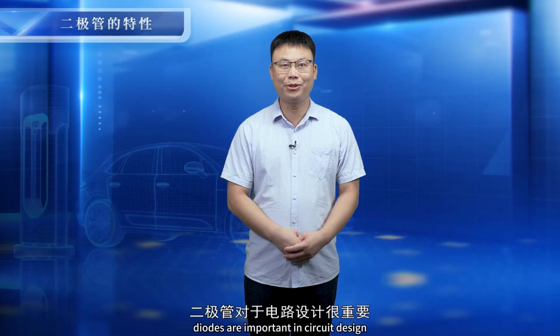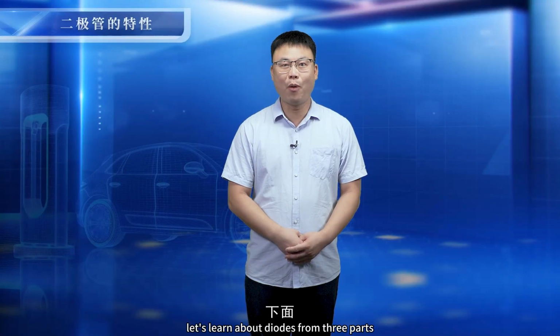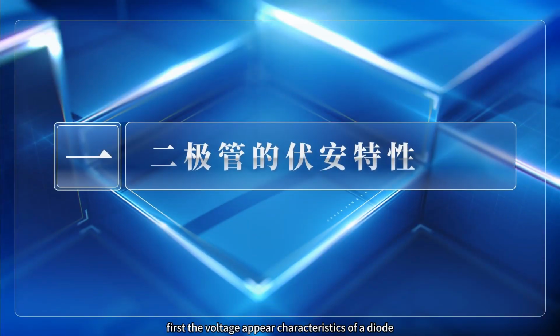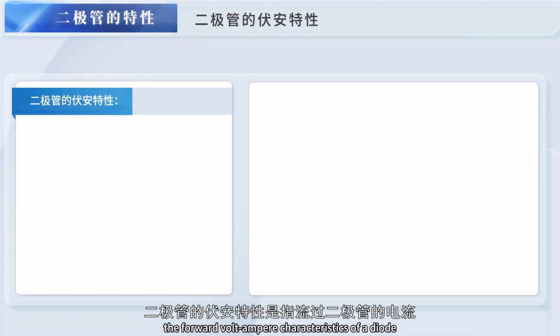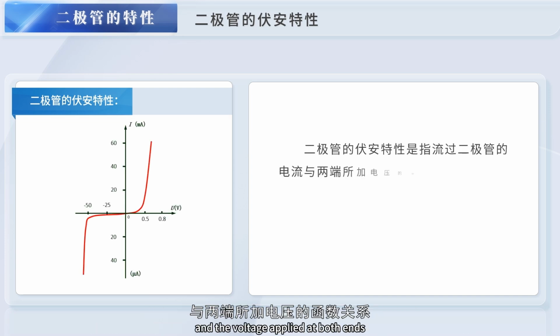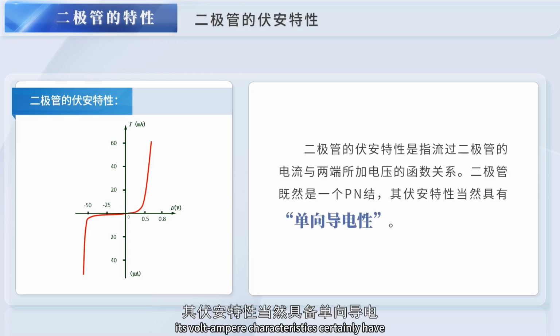Diodes are important in circuit design because diodes have many special properties. Let's learn about diodes from three parts. First, the voltampere characteristics of a diode. The forward voltampere characteristics of a diode refer to the function relationship between the current flowing through the diode and the voltage applied at both ends. Since a diode is a p-n junction, its voltampere characteristics certainly have one-way conductivity. The voltampere characteristic of a diode is non-linear.